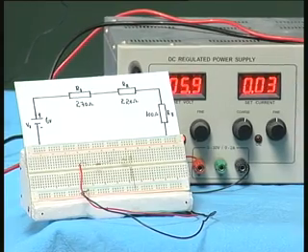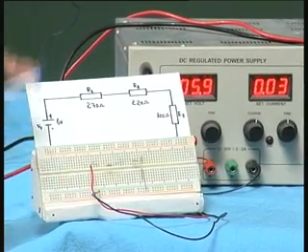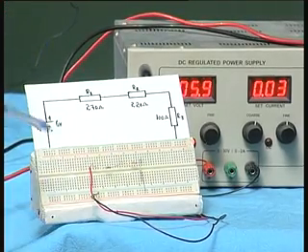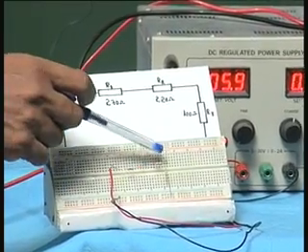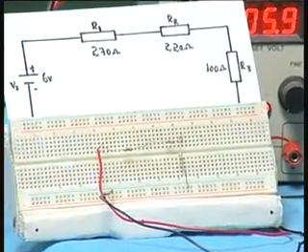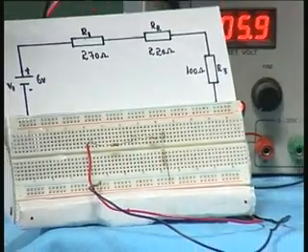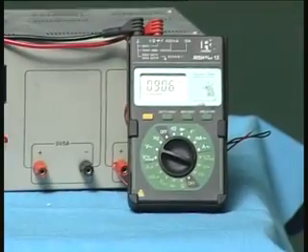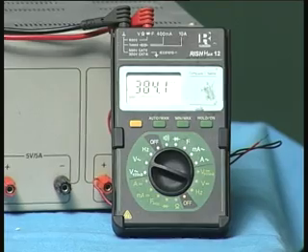Now, what Kirchhoff's law says is that this voltage of 6 volts should be dropped across all these 3 resistors in total. Therefore, if I know the current, I into R1 plus I into R2 plus I into R3 should be equal to 6 volts. Now we have a multimeter which I have switched on and connected to voltage, and it is now measuring DC volts. I have the 2 leads of the multimeter.